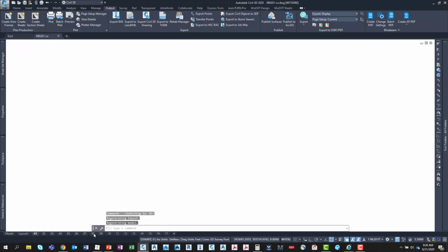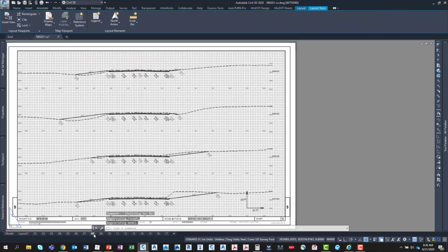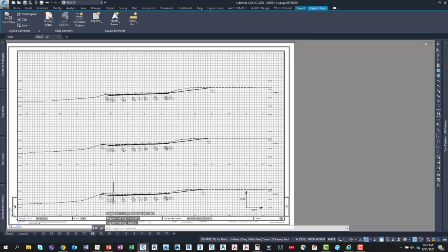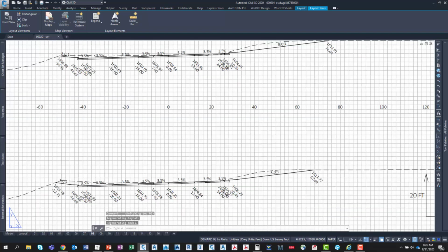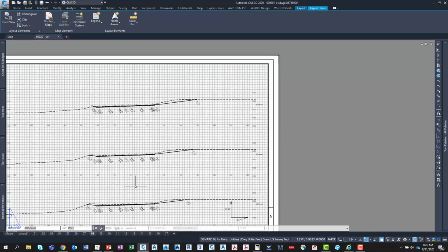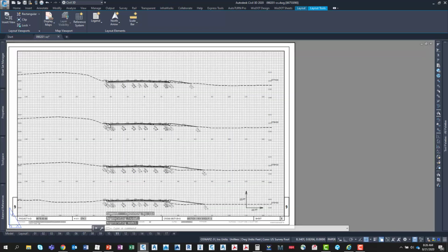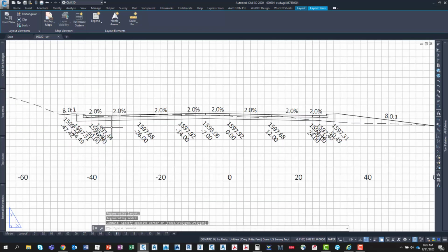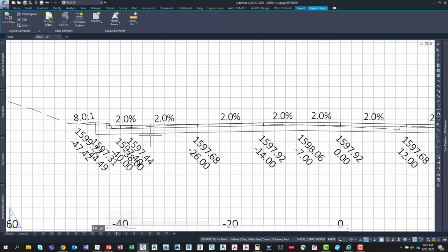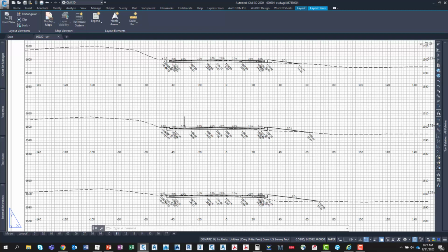We can just go and double check, see how those shapes look on the cross-section sheets. If I zoom in, I picked an area where the datum surface is not showing. There we go. And it has to be with the corridor surface. And perhaps I didn't update the refinement surface. But nonetheless, here we are. So we can see the refinement top, refinement datum, and then the corridor shapes in the cross-section views.